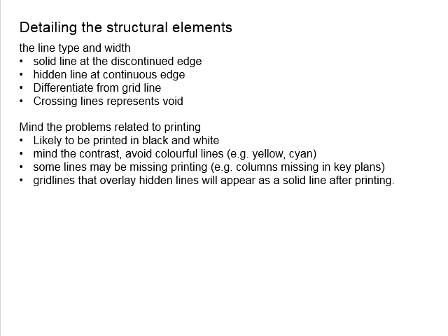In order to resolve this, you have to change the line type, or you use a totally new file in AutoCAD, move the drawings into that AutoCAD file under certain preset line types, and you try to print it again, to see if there are any missing lines. If the problem persists, you might need to troubleshoot what is the reason behind it. Personally, I don't have the answer for this. If you could, give me some ideas. What is the main reason for it?